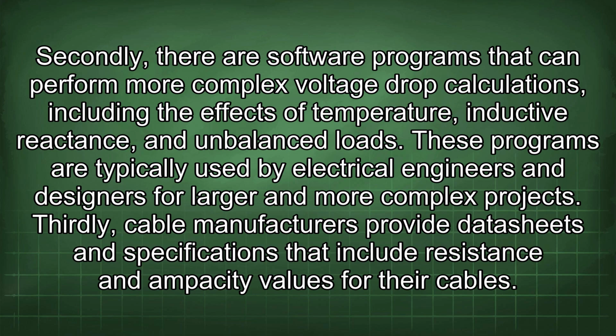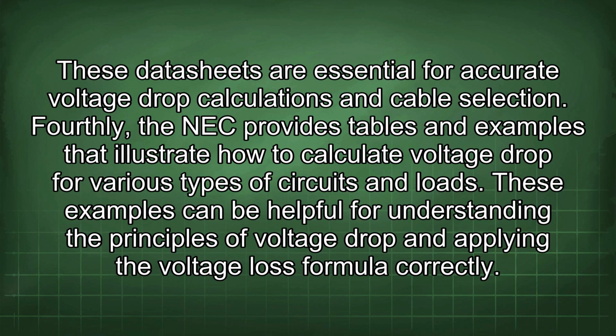Thirdly, cable manufacturers provide datasheets and specifications that include resistance and ampacity values for their cables. These datasheets are essential for accurate voltage drop calculations and cable selection. Fourthly, the NEC provides tables and examples that illustrate how to calculate voltage drop for various types of circuits and loads. These examples can be helpful for understanding the principles of voltage drop and applying the voltage loss formula correctly.